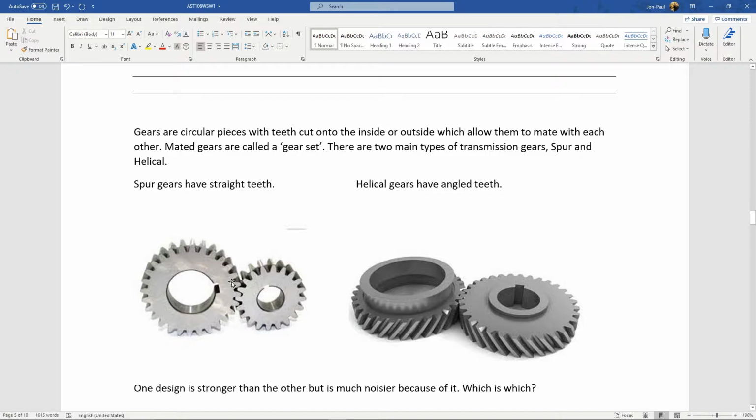And so in this one right here, if we were going to say first gear, it would be these two gears. And right now, I want you to walk away from the notion of first gear, second gear, third gear, fourth gear. We're going to do it like the artist formerly known as Prince. The gear ratio that you used to call first gear is actually whatever gears. And it gets even more complicated in the automatic transmission with planetary gear sets, because those planetary gear sets never disengage, which is a tricky little thing.